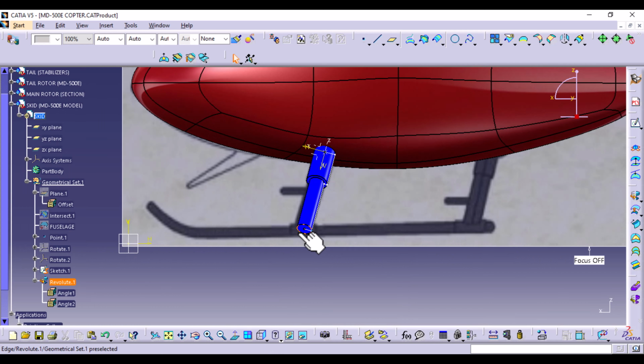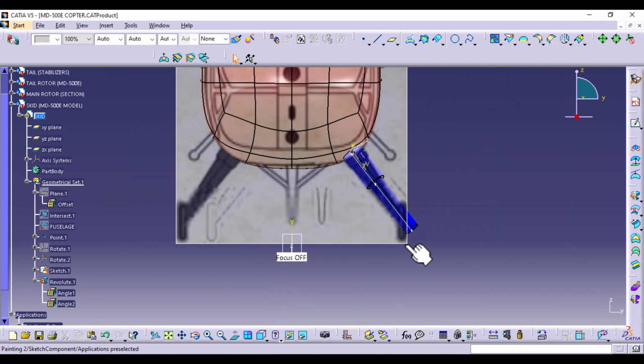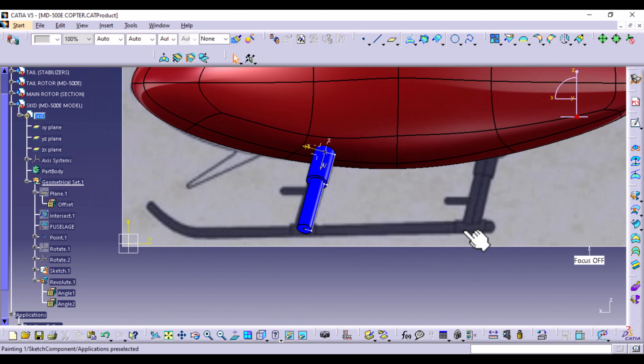And then we're still going to split this surface. So it doesn't matter if it exceeds its length. We're just going to split it at this point if that's where we are going to have our horizontal skid. So that's good. To create this skid, I'm just going to assume that it has the same inclination in terms of the side view and also the front view. So we can just translate this object up to this point. No need to create another one.